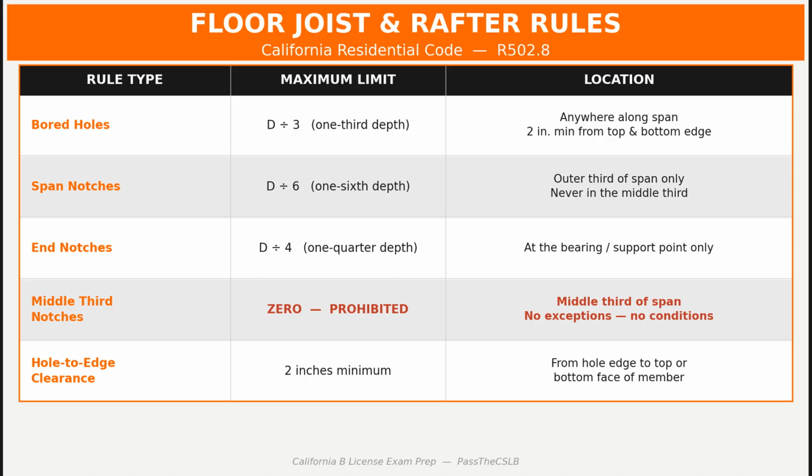And I will add this because experienced framers know it, and the code supports it. Square or rectangular cutouts are not recommended. Square corners concentrate stress at precisely the point where the notch begins and are where cracks initiate under repeated loading. Angled cuts distribute that stress transition more gradually.